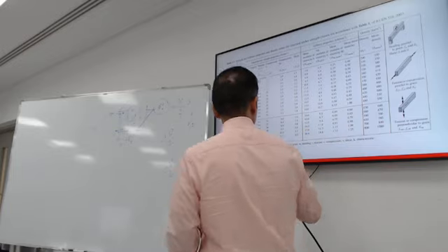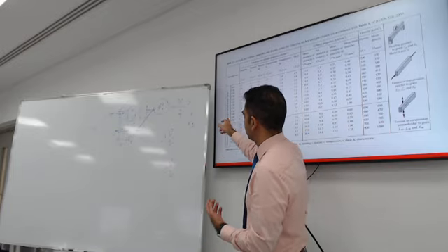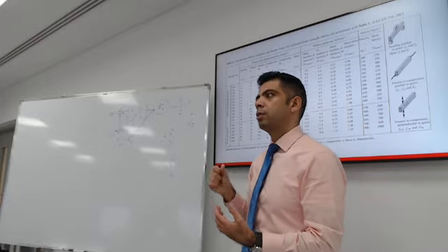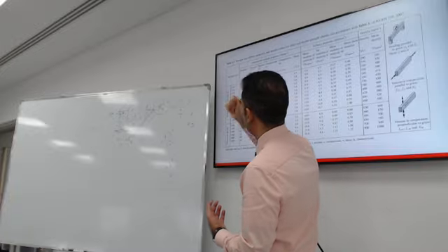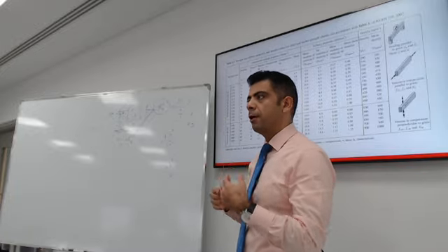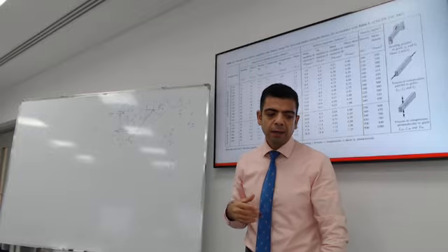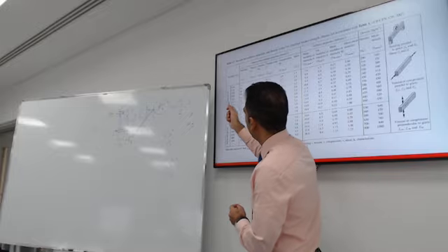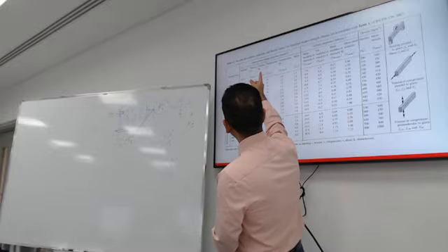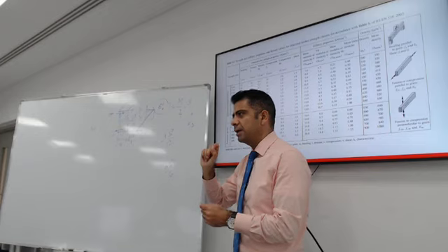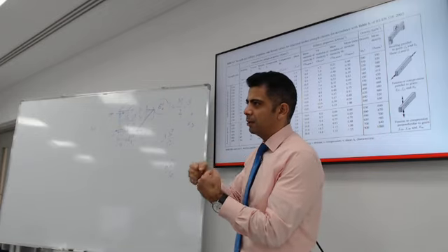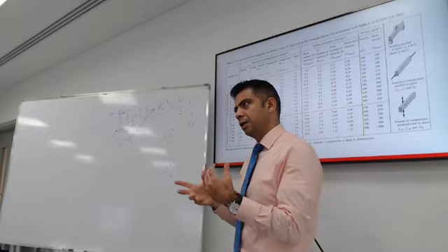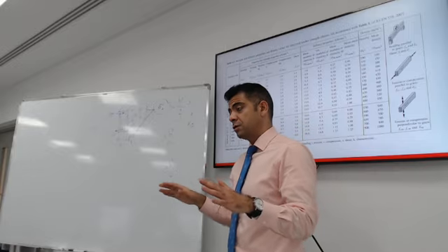There is a note here that you might find it difficult to get a grade like C45 or C40. It's going to be a very rare product, but the lighter, less strong grades might be readily available. I want to take you through some of the things that you might find. The characteristic strength property, you can think of it as the ultimate strength of wood. It will be like the fy kind of thing. But it's very dangerous to think of yield when you're dealing with wood. It's a different material, so don't mix the two concepts.